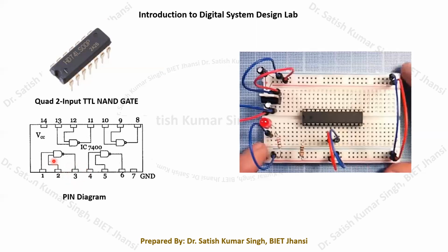Okay, so first of all, the important point that we need to remember is how to identify the pin numbers. So always you have to count the pin numbers from this C group. Okay, once you identify this C group, then from here only you have to start counting your pin numbers. Okay, and then you have to go anti-clockwise, and then you will find all the pin numbers. Okay, identify the pin numbers, and then you need to know this internal pin diagram.